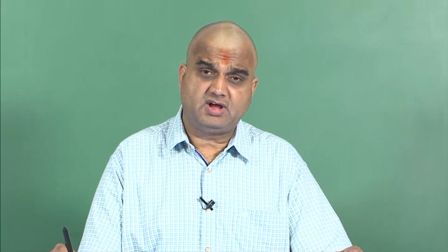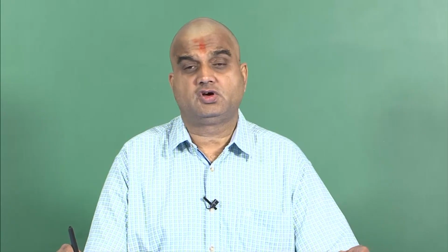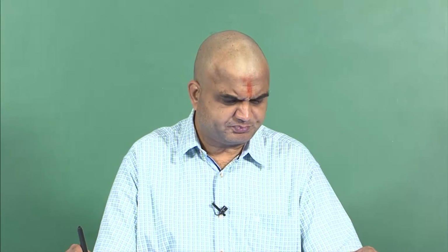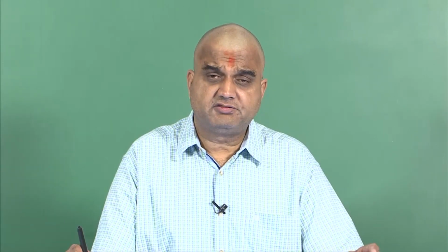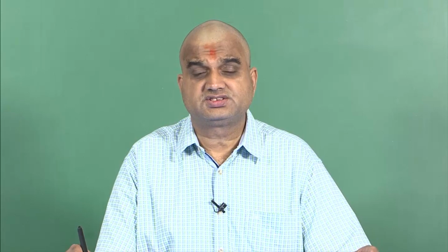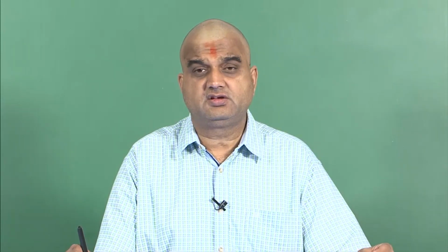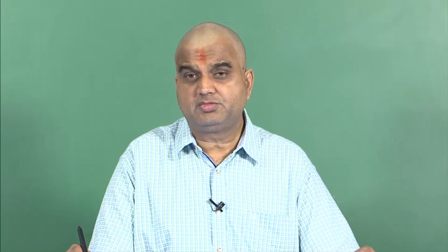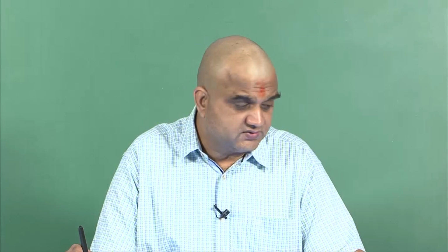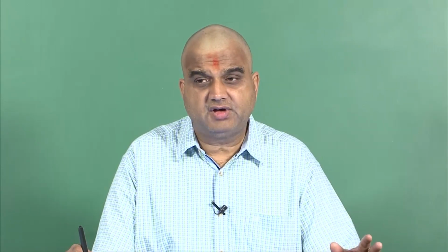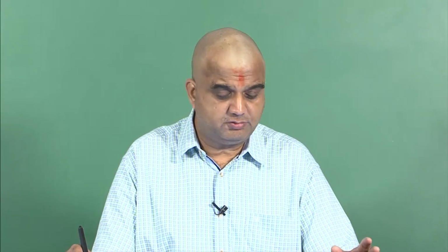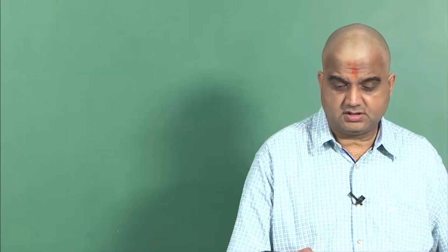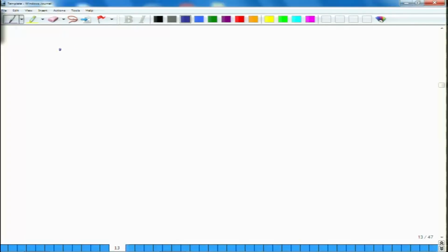And what we found while developing the moment equilibrium equation for the third axis, that is the z axis, is that the fact that tau xy equals tau yx means nxy equals nyx, and that implies directly that the sixth equilibrium equation will be identically satisfied. So, effectively we have only 5 mutually independent equilibrium equations, and we will again rewrite them and process them further. So, what are these equations?